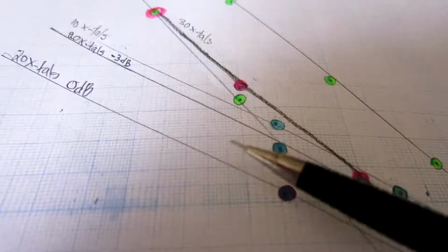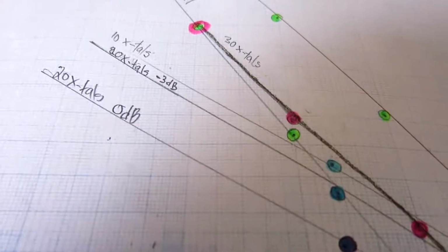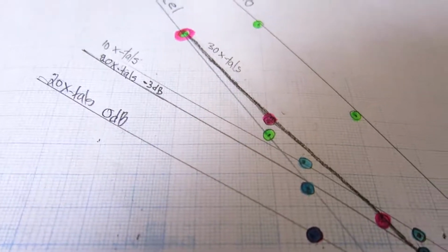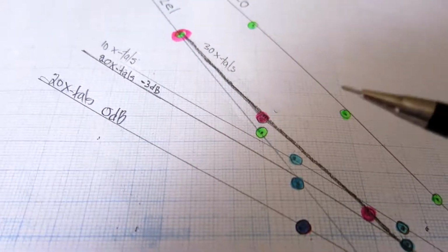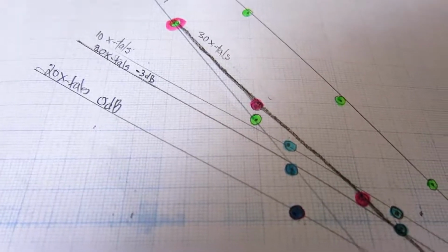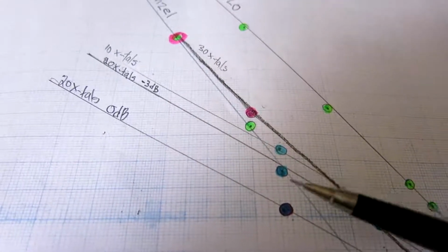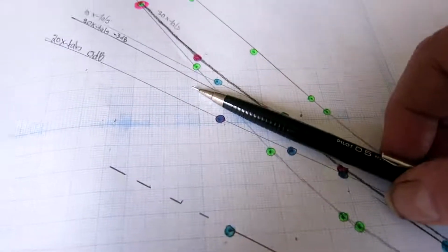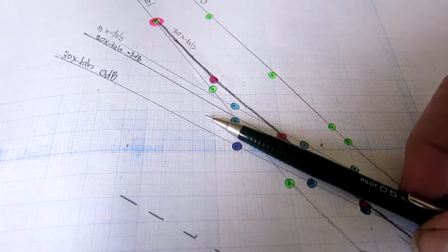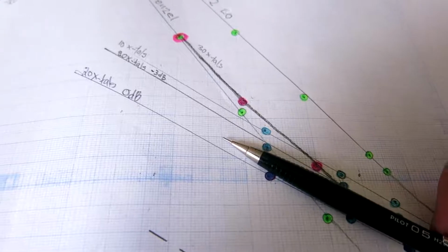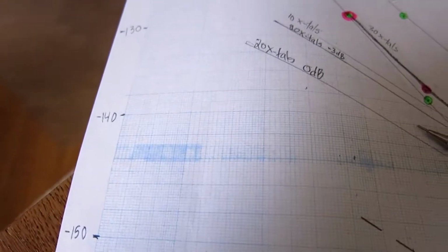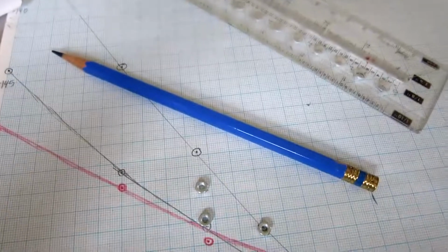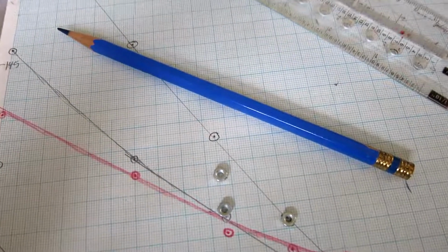Anyway, I have studied both with direct measurements similar to what I'm doing now, using another Wenzel oscillator, but also with interferometry, and get similar results. So these curves, they have the appropriate slope for flicker noise, and they are at about minus 144 at 10 Hertz. So those lines approximately fall where I have placed this pen.